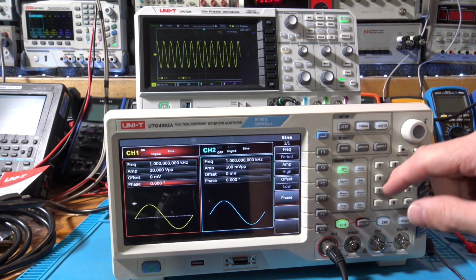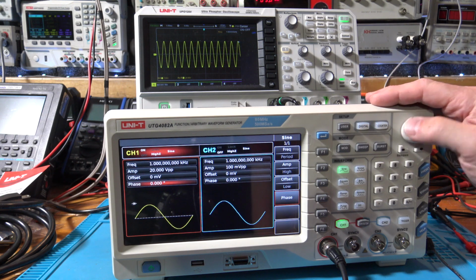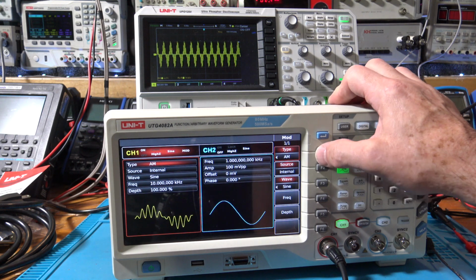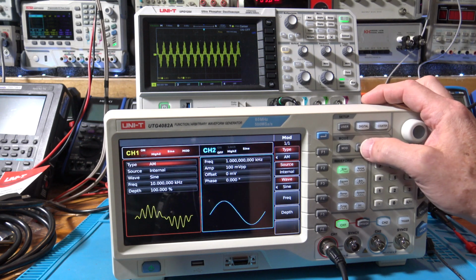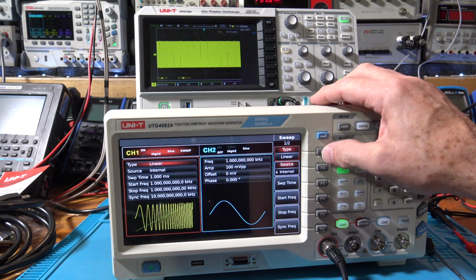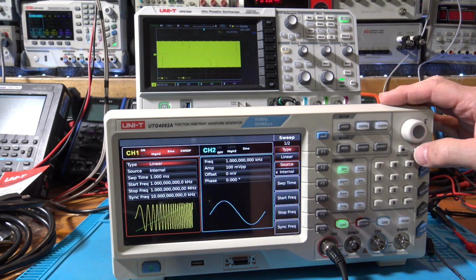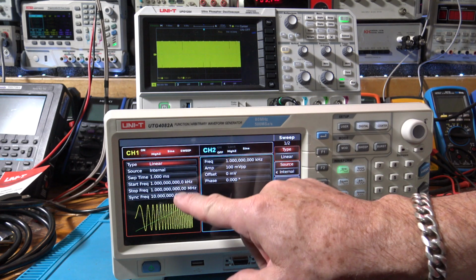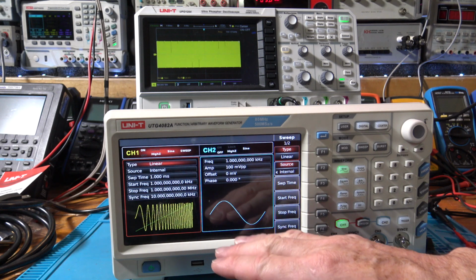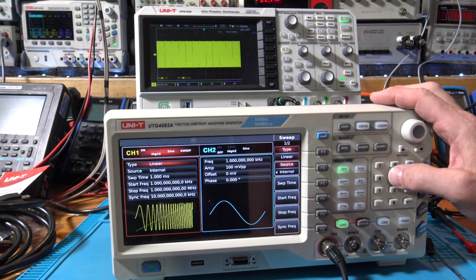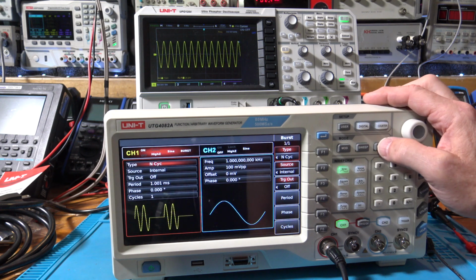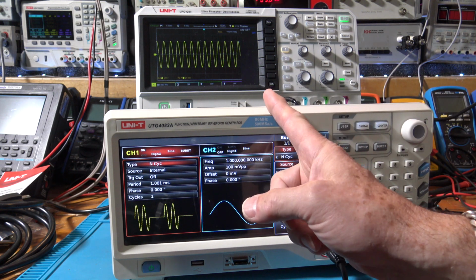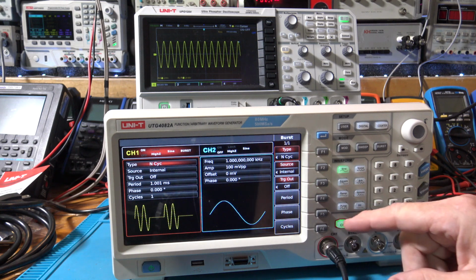Okay, so that's all your outputs. That's your frequencies. Lots of frequencies. Let's look at the modulations again. I mean, lots of modulation types, right? But I also have the sweep one. So I have linear and log, right? Just like before. And you can set up your start, stop, and, you know, all that kind of stuff. So really nice display. A lot of information there. And then, so modulation is sweep, and then here's burst. So you can go back to burst. And very similar to 1042 up above. I mean, you can see how each one is just giving you more and more features, though.